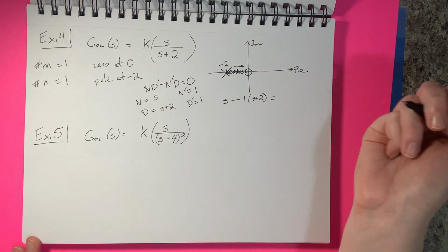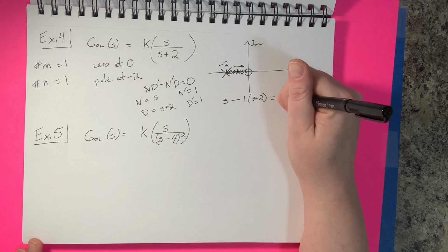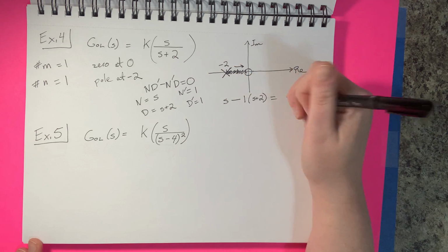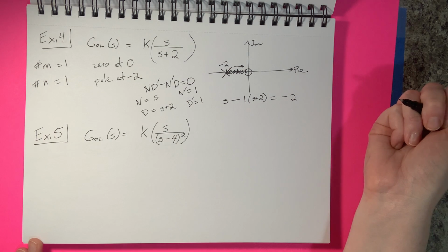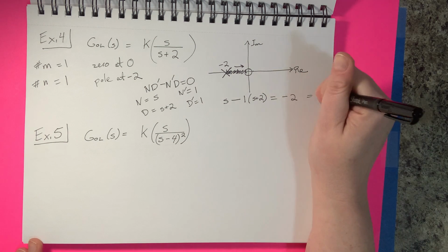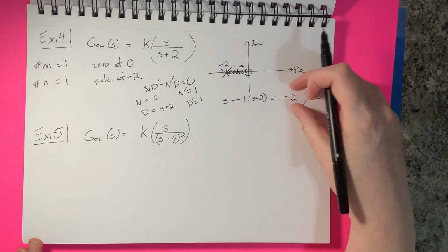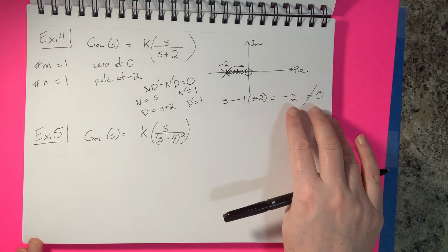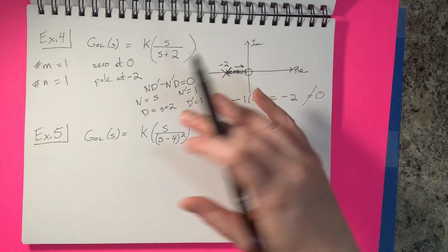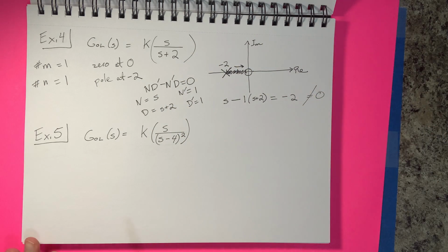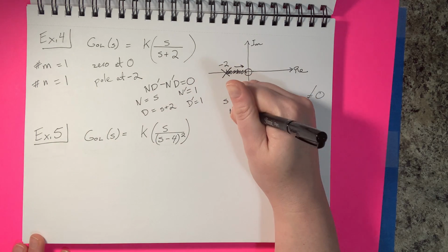Okay. All right, so it looks like we've got s minus s, which is 0s, and then we have just a -2, okay? And that doesn't really make sense at all with respect to setting this equal to 0, so we can't have that at all. So we have something that does not make sense, it doesn't solve correctly. So in that case, we can see that we definitely do not have any breakaway points. We don't have any possibility of them. Okay, so we'll just write that conclusion.